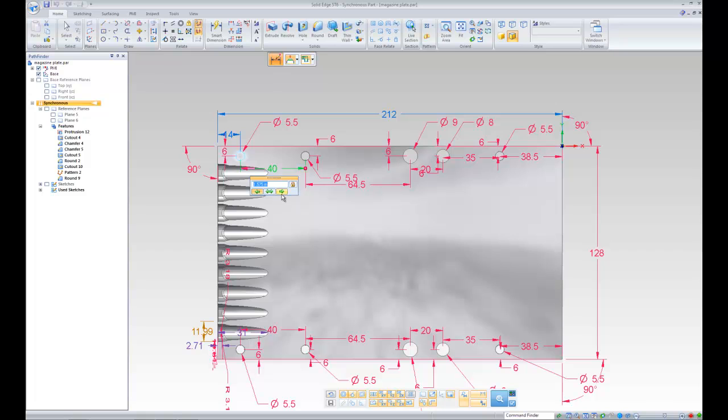Now if I wanted to change that, I could come in here and I could lock down this dimension in this direction. I can lock down this dimension in this direction, and at that point in time these two holes will always move relative to the end of this part here. So there are a number of ways you can create predictable behavior depending on how you lock down parts. If you want to do a family of parts, locking down dimensions to important features is one way of doing this. And for instance, I could grow the overall length to fit different machines. If this hole and this hole and this hole and this hole, for instance, were required to be attached to the end faces, we could stretch this block and have it do so and create a new part simply by editing a dimension or two. In any case, the power of locking down dimensions and how you lock them down is very important.